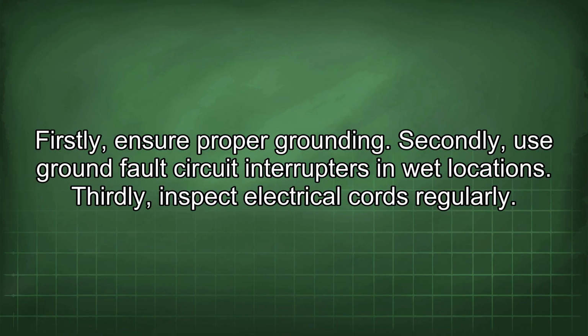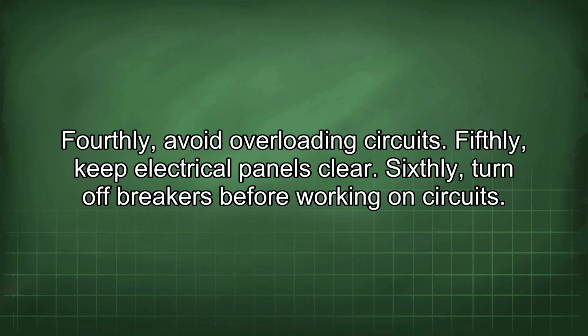Firstly, ensure proper grounding. Secondly, use ground fault circuit interrupters in wet locations. Thirdly, inspect electrical cords regularly. Fourthly, avoid overloading circuits. Fifthly, keep electrical panels clear.